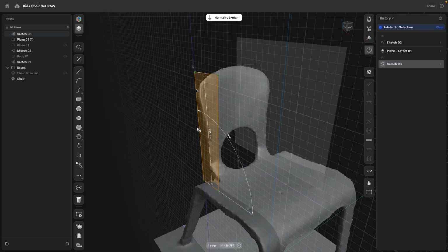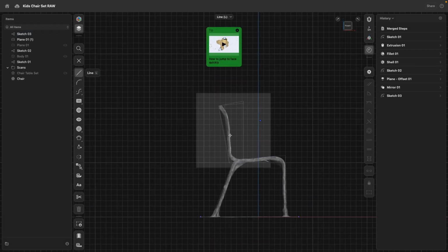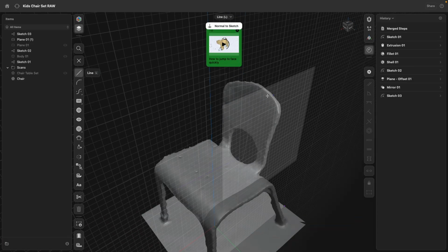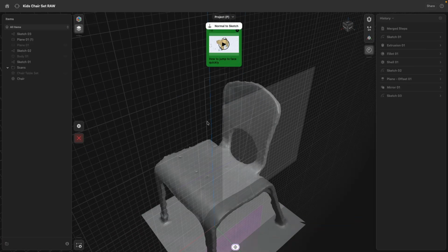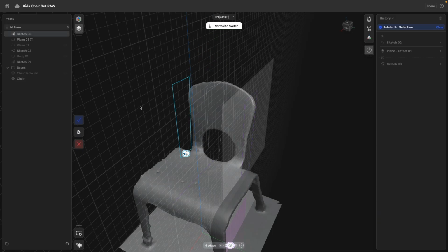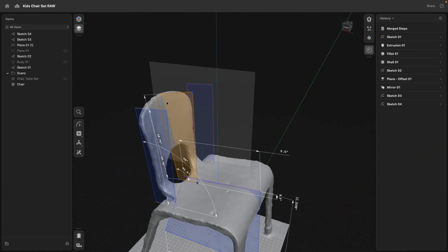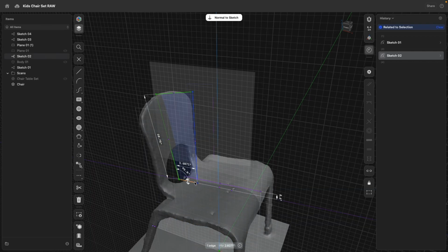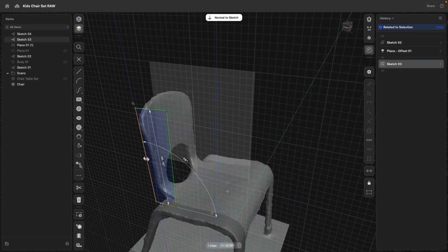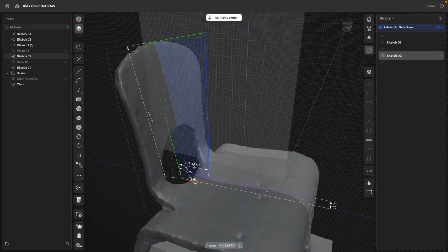And now this sketch I would like to project over there. So I'll make a new sketch on that construction plane. Then I will hit project and simply project those elements over. Done. So because we do these projections, that means this lower line is projected into this sketch, aka that means when this one will be adjusted, for example, I make this 4.